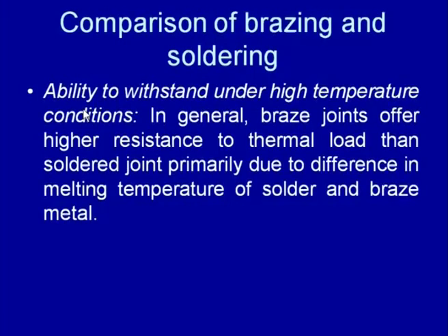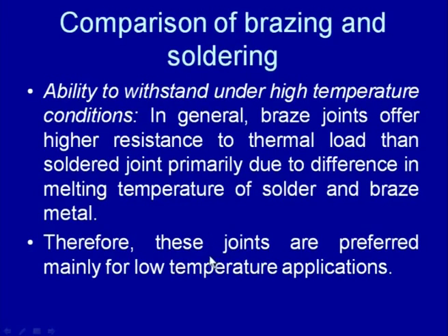Then, on the ability to withstand high temperature conditions, in general braze joints offer higher resistance to thermal load, meaning they can withstand high temperature or higher thermal fluctuating conditions than solder joints can, and this difference is primarily due to the difference in the melting temperature of the solder and the brazing filler metals which are used, and therefore solder joints are preferred mainly for low temperature applications.